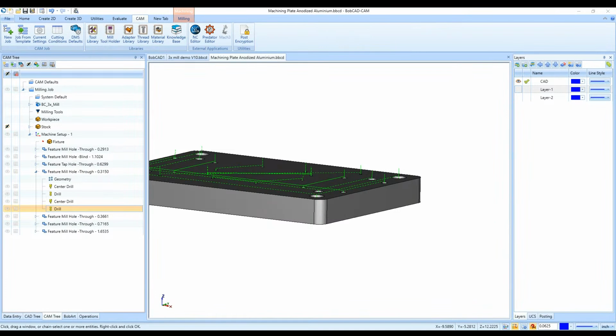We've got our pecking options. So we can set a certain formula here to save as a certain default setting. For this one, if the depth of the hole is less than 3 times the diameter, it'll do a single depth. Here we get out our math calculations.